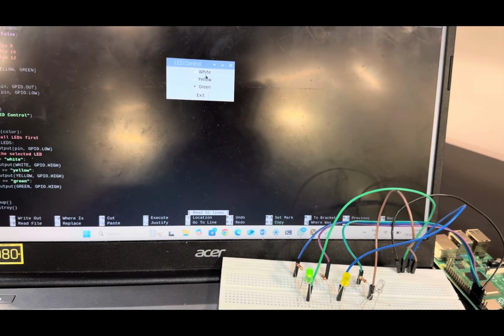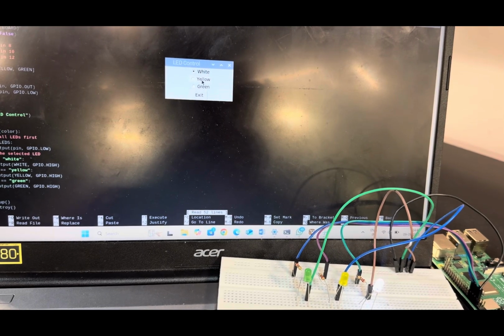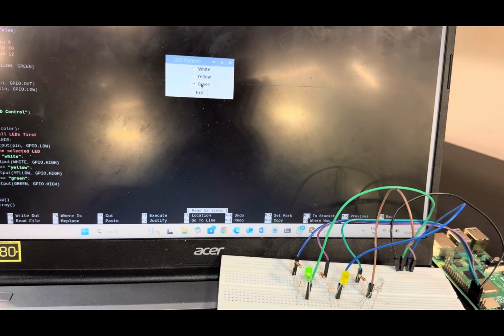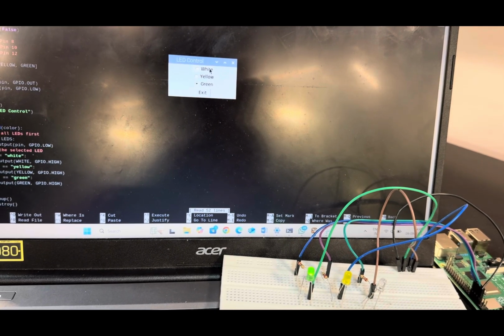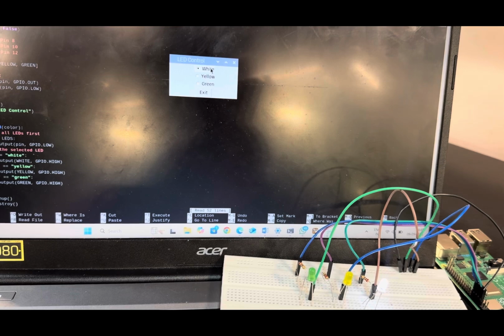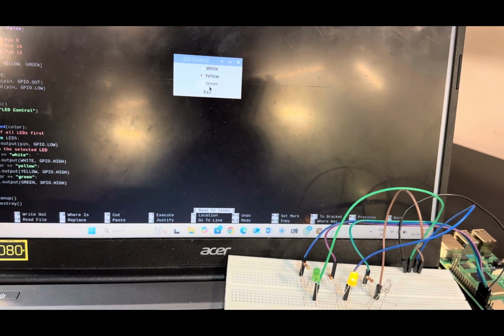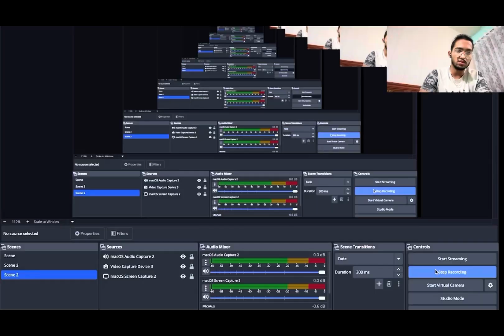These are some important libraries required for this task. After that, we are doing the GPIO setup by assigning the pins, and then we are running the loop for the LED setup and making the GUI so that we can see the buttons. When we click on the buttons, we can turn the LEDs on and off using the GUI.